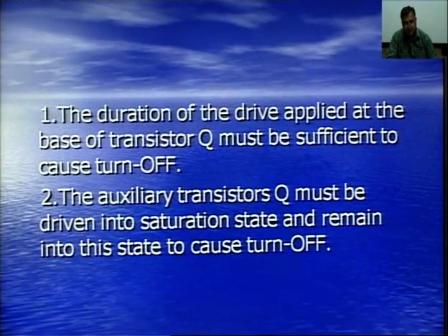Number one, the duration of the drive applied at the base of the transistor Q must be sufficient to cause turn off. Second condition is the auxiliary transistor Q must be driven into saturation state and remain in that state to cause turn off.